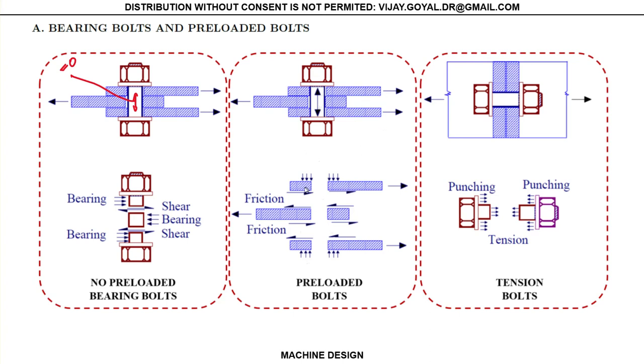So it's mainly a matter of what the members can handle and whether your bolt can handle the stress here. It's rarely going to fail in shear. It can, if it exceeds the friction value that I apply between the mating surfaces.